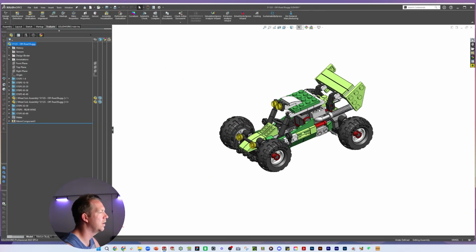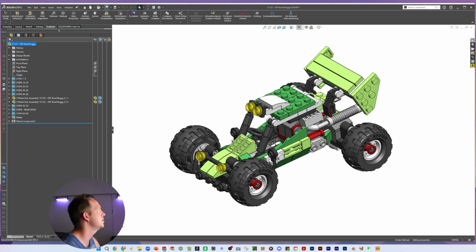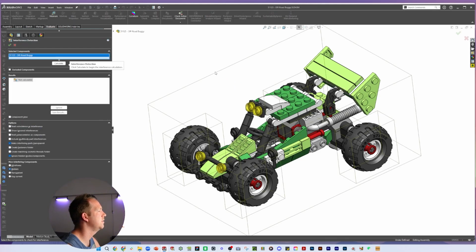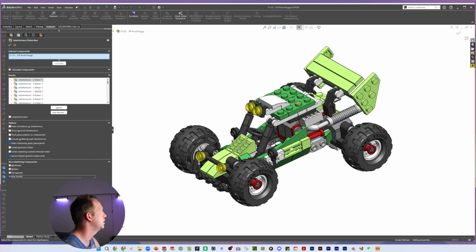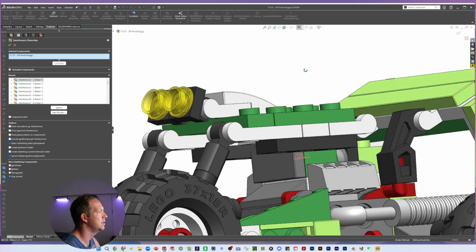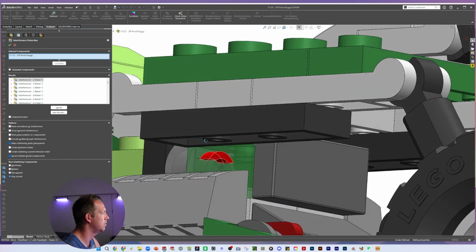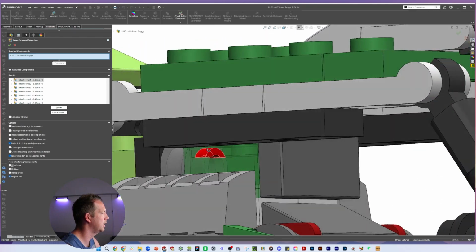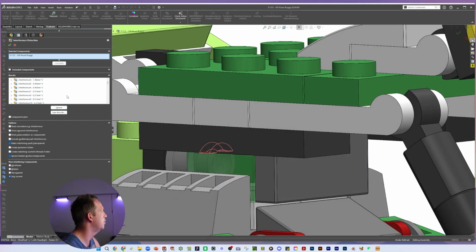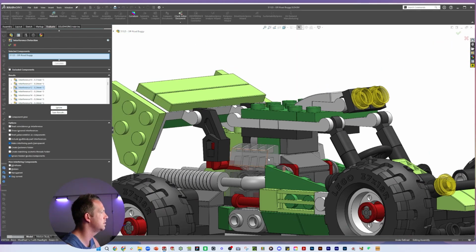All right, so we've only addressed a couple of interferences there. Let's just save, do another interference detection. And you can see our interferences, they're now getting, there's less of them. There's still a lot, 133. But there's a lot here that are 0.19, 0.22. I'd say as we go through and adjust some of these sizes, a lot of them are going to get removed if we fix whatever it is, this one.